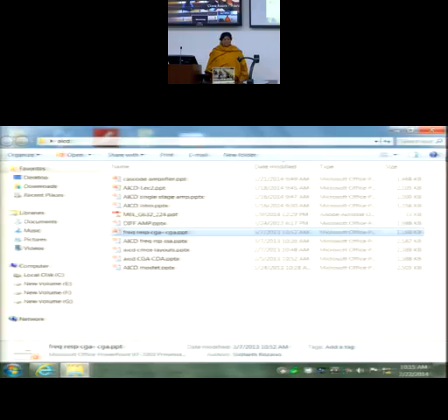Then we said, okay, common source amplifier is a single stage, what other configurations are possible? We looked at them. We looked at their DC parameters, low frequency small signal gain, R in, R out. Then we asked, what is the impact of high frequency signals? How do these circuits behave when a high frequency signal is given? Accordingly, parasitic capacitances come into the picture. So every node now becomes a capacitive node, and hence there is a time constant associated with it. So finding poles and zeros. We did this for a single stage.